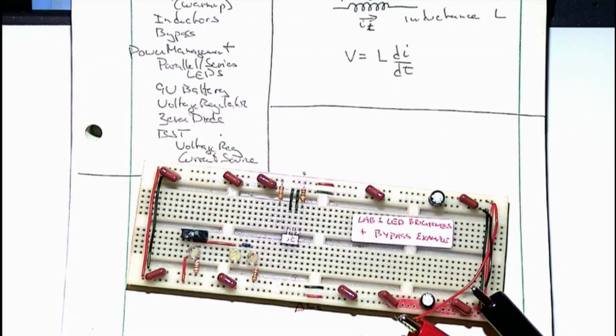All right. What I have here, these are my bypass caps. The size doesn't matter. 0.01, 0.1, anything you got. In fact, we have a drawer in the parts cabinet that says bypass caps, and it's just all of our bypass. People who didn't want to sort capacitors, we threw them in there because it doesn't make a difference. You know, I put one in about every inch or so.